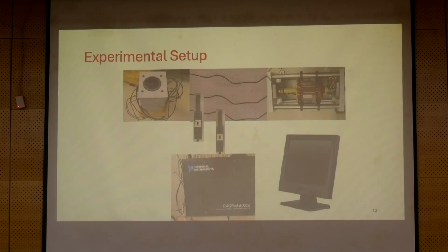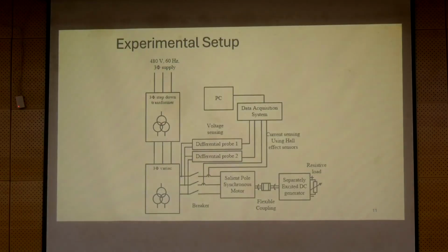Exactly. So most of the modern oscilloscopes already have digital storage capability. The only thing you may have to check is the resolution of those oscilloscopes' ADC system. If they are 8-bit resolution, it might work out, it might not work out. So you have to try it out, okay? Depending upon the voltage signals and the current signals you are working with. Yeah, so this is the major thing. So this is what I used.